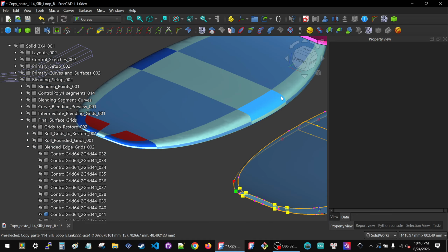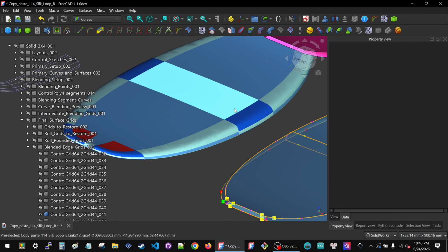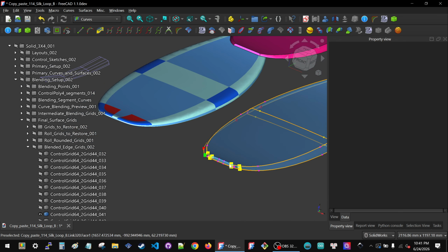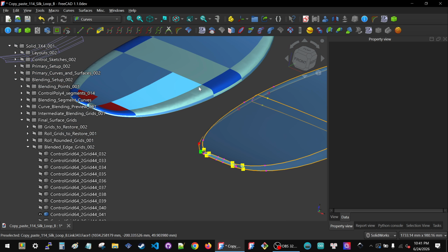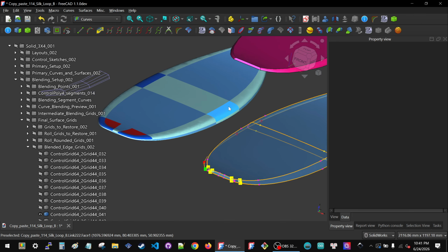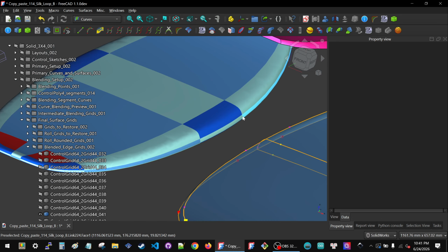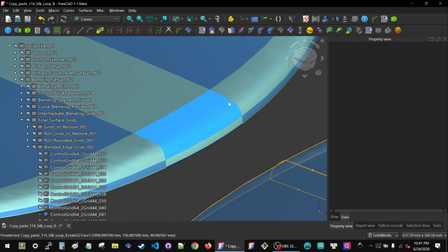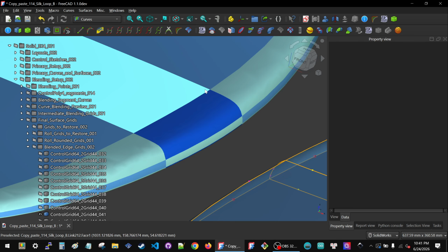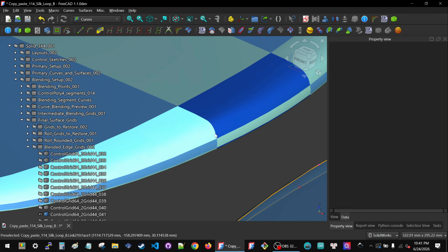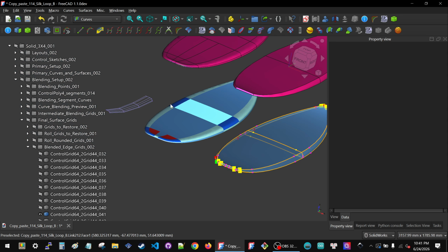So what this does is it allows me to vary the size of the blend, to vary the effective size of the fillet action within the blend at a given blend size. See, because the blend size is where it cuts into the surface. The fillet action is how much it pinches. So here I have a very soft filleting, which means it curves the whole time. More so on the vertical face because the vertical face is smaller, but it rolls the whole time. And here I have pushed the rounding action towards the top.